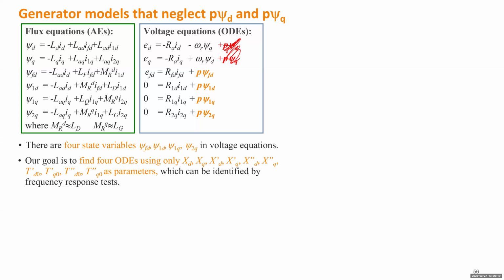Earlier, if you look at all the parameters in the flux linkage equation and voltage equation, they are inductances and mutual and self-inductances, but it's not very clear which one falls into which time constant, which one is associated with transient dynamics, and which one indicates a faster dynamic. But the ones we derived in the previous lecture, like Sd, Sq, Sd prime, Sq prime, and double prime, and also T single prime and T double prime, are very clear in indicating which is associated with subtransient dynamics and which with transient dynamics.